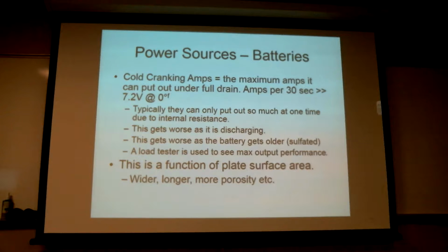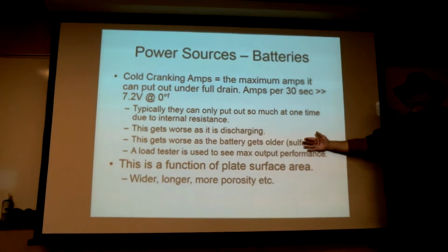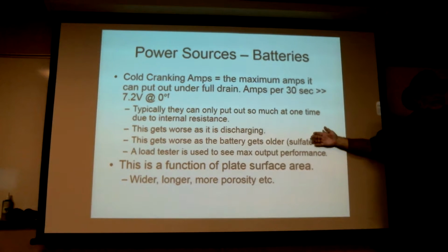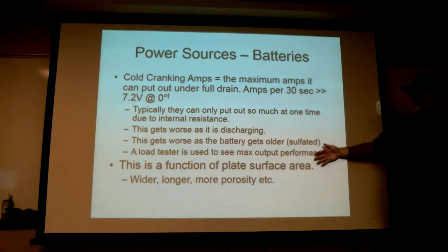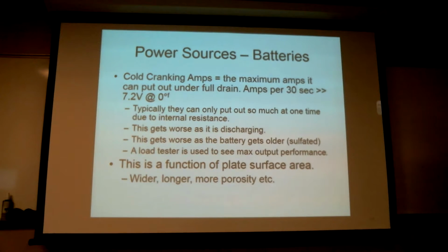Okay? That tells you that in spite of the fact that it charged, in spite of the fact that the fluid looked okay and everything looked good, there is some internal shorting down in the battery, and this battery needs to be taken out of service.